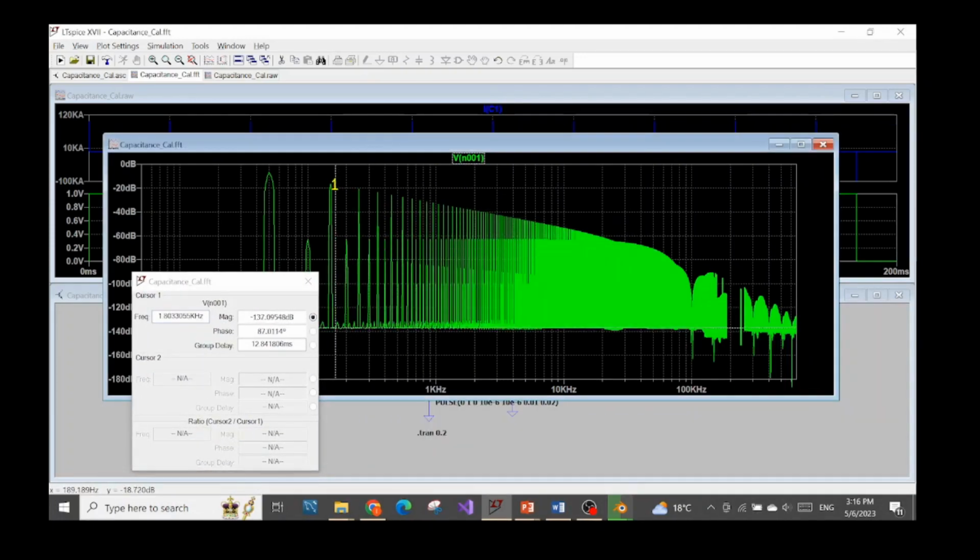For example, here of course we have a peak. It means we have some signal. So we had better choose a peak in order to have some signal to calculate. Don't choose something like down here. That's noise. Now we can choose this signal, with the voltage at a frequency of, let's say, approximately 150 Hz. So that will be our frequency of interest, from which we will derive our capacitance.